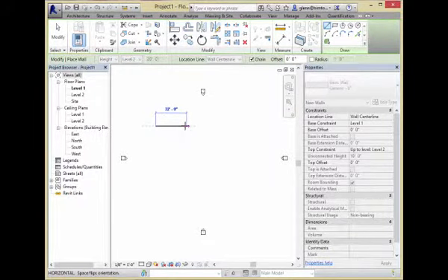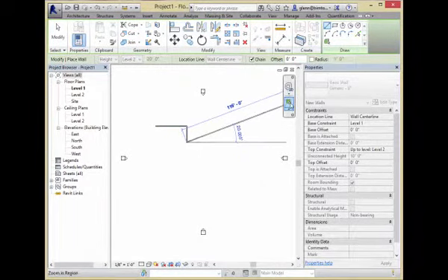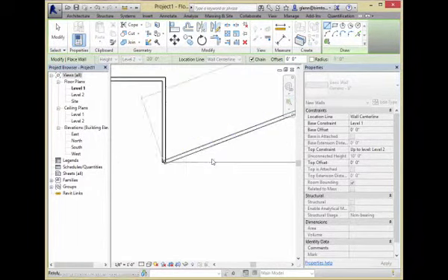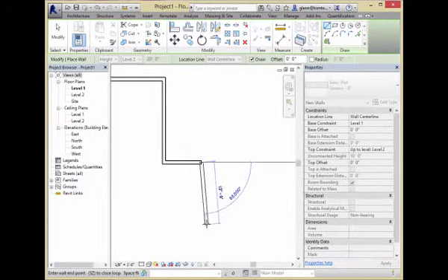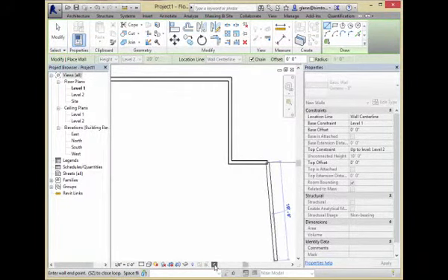Okay. I'm going to draw some walls, just stretch them out here. Notice they're set to wall center line, and let me even zoom in to give you a highlight of what's going on. As I draw the wall, notice there's that little green dashed line, which is indicating where I'm actually drawing the line. You can see the wall's being centered on that. Okay, and that's okay. For generic walls, it doesn't really matter a whole lot. You can leave them centered, and they work out okay.